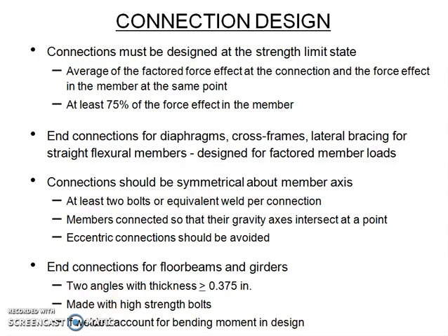Now the end connections for diaphragms, cross frames, lateral bracing, and other members are all designed for factored member loads, because we are following the limit state, and as per the limit state we consider up to the plastic stage of the element, and therefore we give it a load factor. Similarly, bolt connections should be symmetrical about the member axis so that the distribution of loads is equal towards the bolts and the welds.